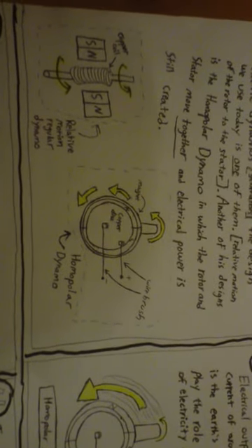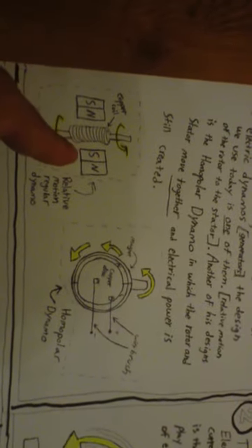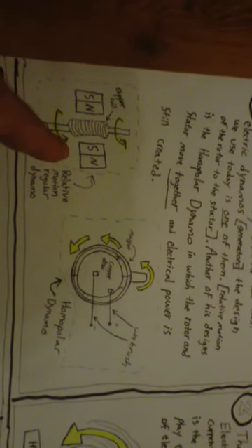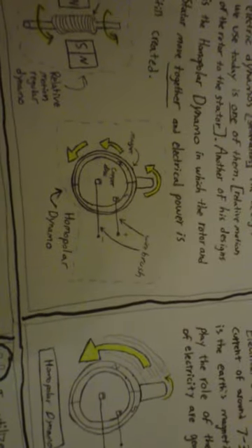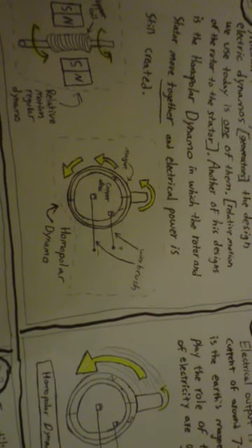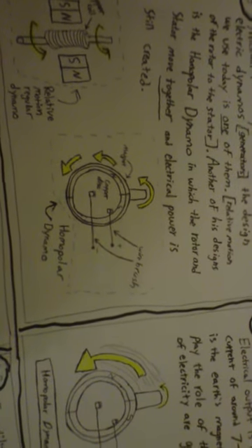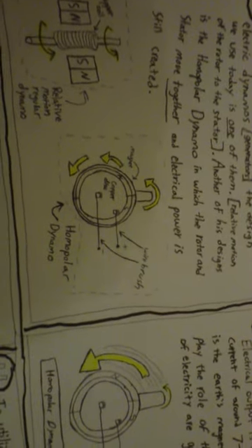The stator and rotor in a homopolar co-rotate, meaning instead of, in this conventional design, the magnet staying stationary and the wires revolving, both the conductor, here displayed as a copper disc, and the magnet rotate together without relative motion between them. This is the homopolar design.